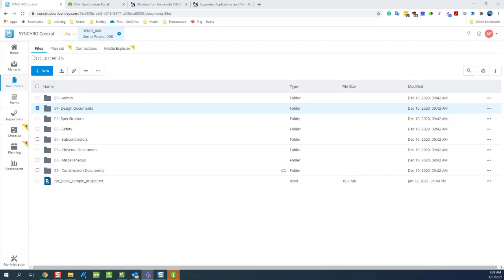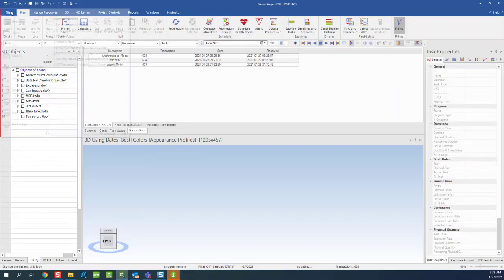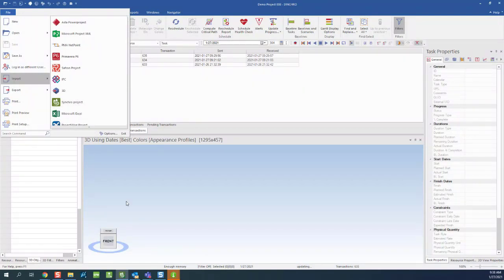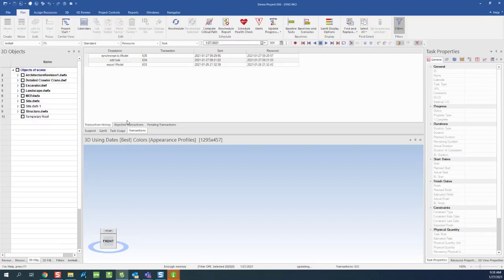That depends. If you already are using SYNCHRO and have a project going on, you'll definitely keep using the SYNCHRO native connectors and file import, the 3D or SYNCHRO project using the SYNCHRO plugins. In some instances, it might be easier. I know for geolocated models, it's better to use the iModel bridges; they deal with them better than the SYNCHRO plugins. It depends on the model type and the software you're working with, and the complexity of the model.